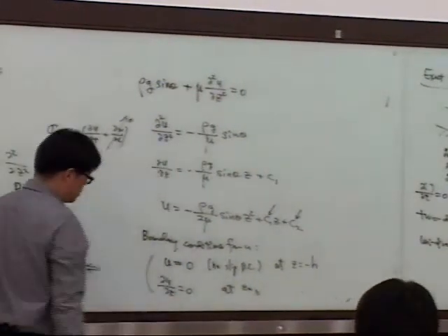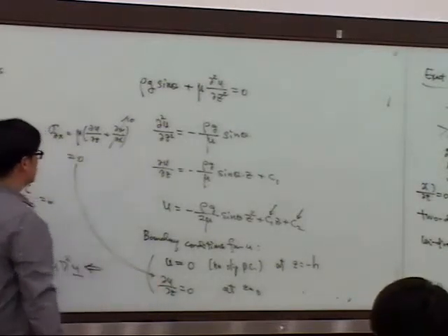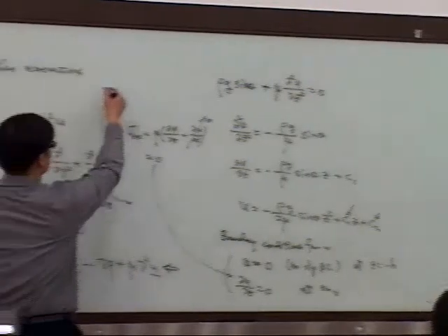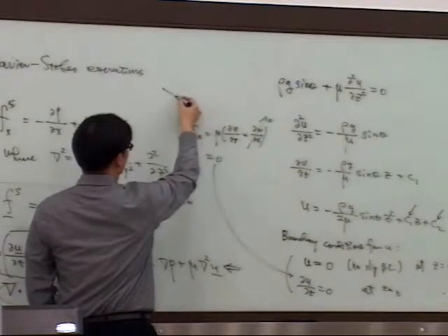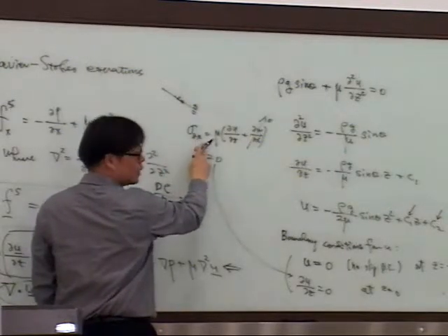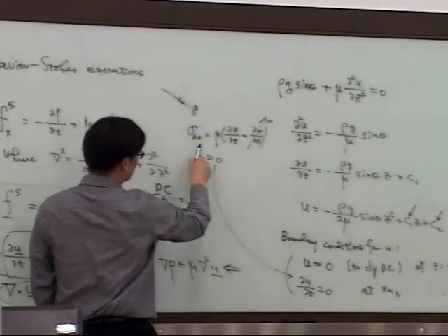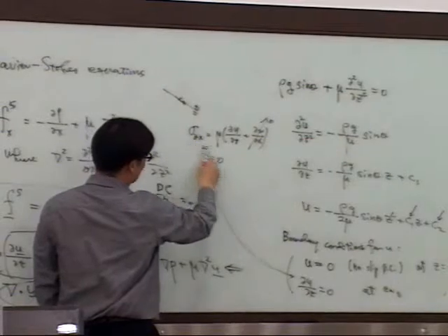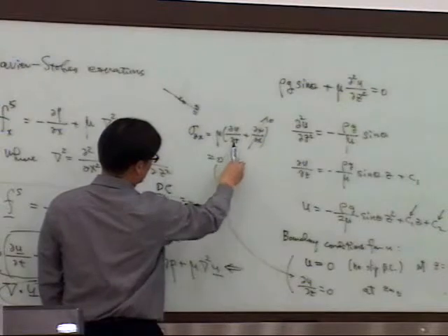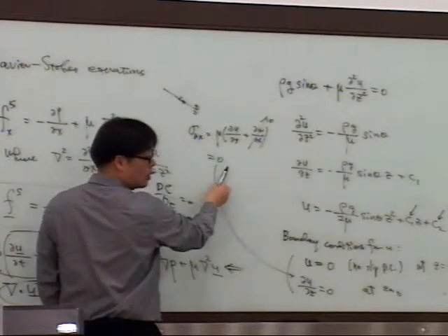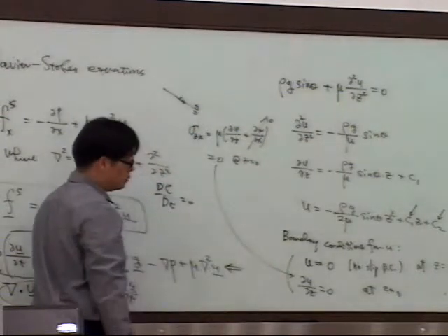So this is the no-stress condition, which comes from here. We are looking at this free surface, and the stress in this direction is given by this, because the normal vector is the z direction, and the force direction is the x direction. That's why we are looking at sigma zx, and W is 0, so all we have is this guy, and this guy has to be 0 at z equal to 0, meaning that du/dz has to be 0.